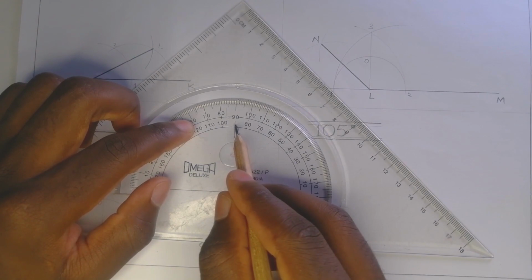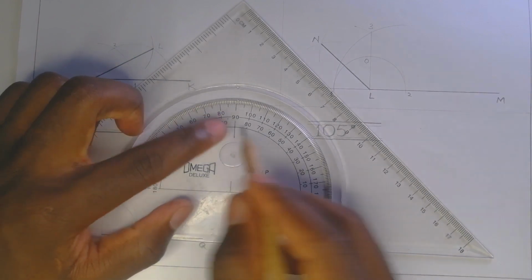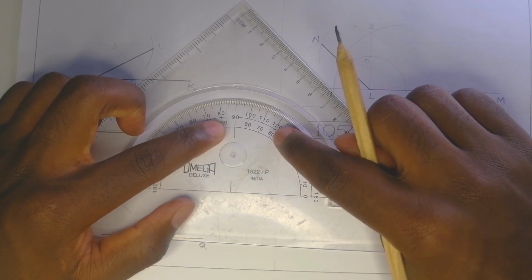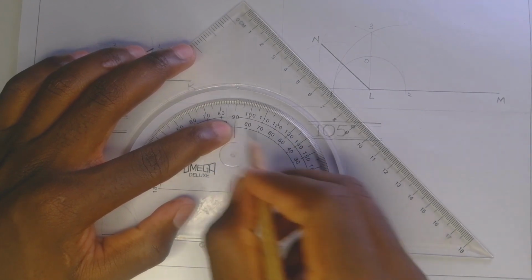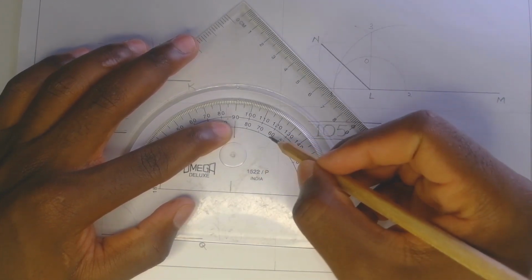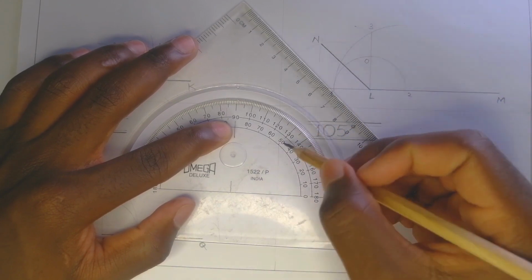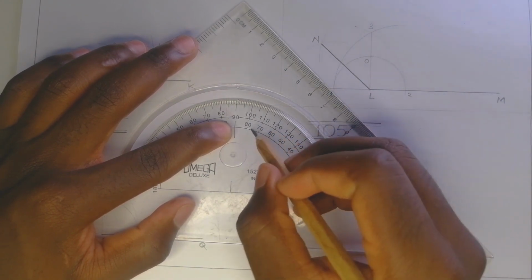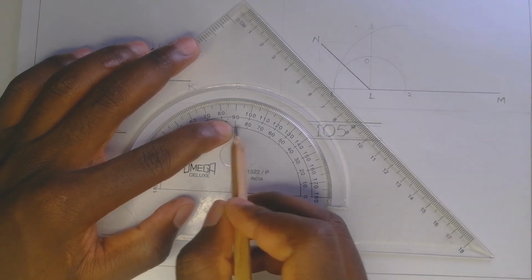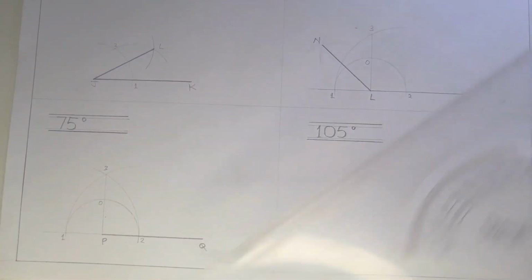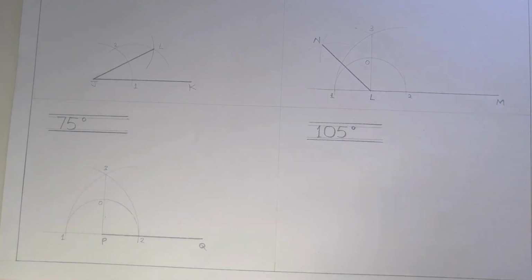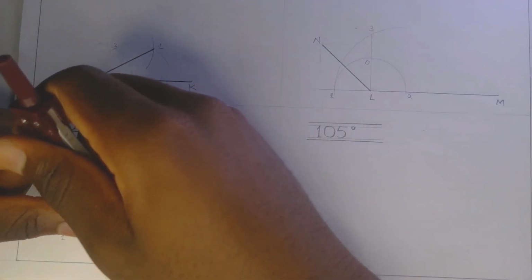Now, notice something very important. When we look at the angle 60 and 90, the difference between these two angles is 30. And if we bisect this angle, it means we're adding a 15 to 60, which gives us 75, or subtracting from 90, which gives us 75. Which means that for us to be able to construct the angle 75 degrees, we need to have a 60 somewhere, right? Great.